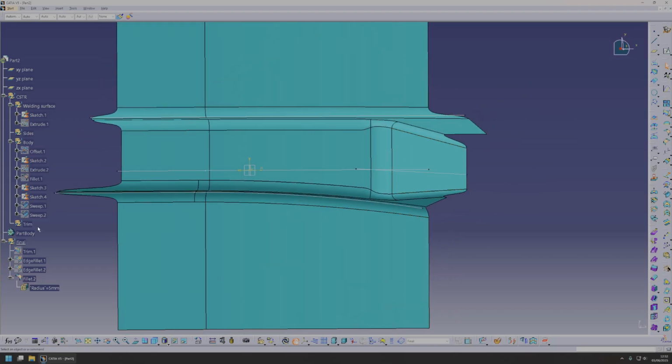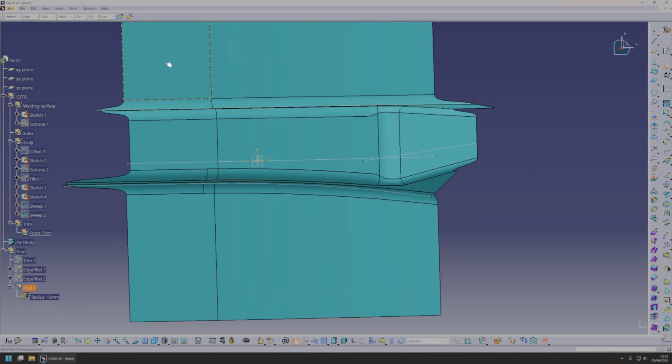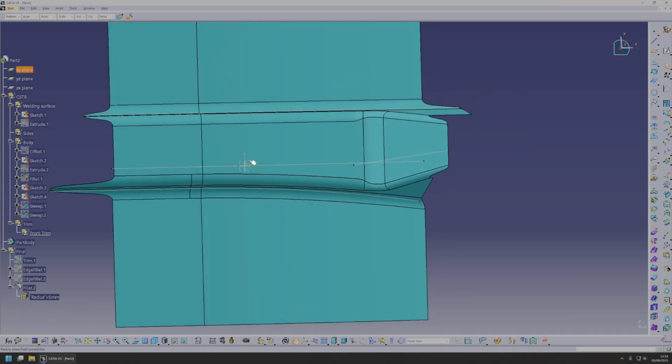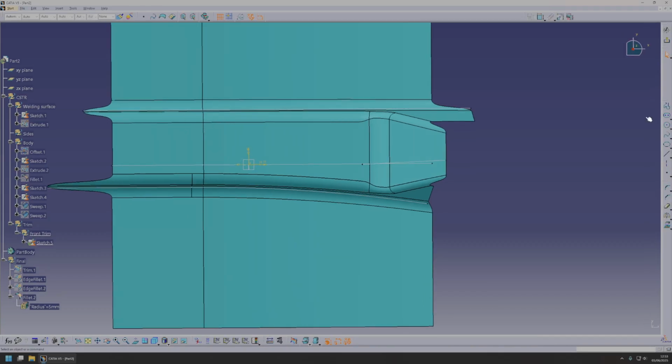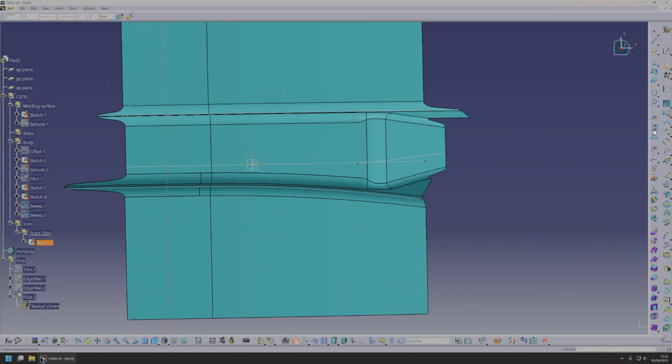Now the first hard part is the trim. First let's split this trim into two parts. So we have the front trim. This is really easy. You just need to cut it somewhere. So basically what you need is a line like that. 40 millimeters should be enough.